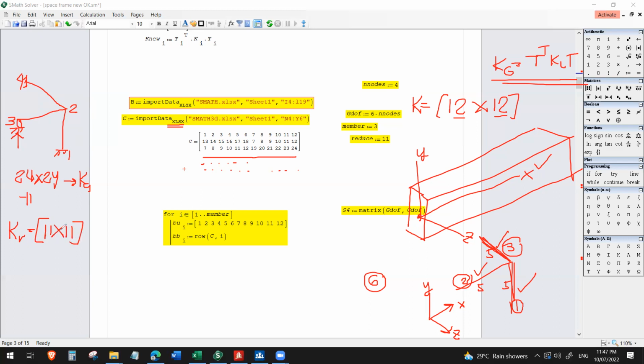So that's the relative stiffness matrix, no? Meaning relative stiffness matrix because we now consider the number of displacements of our structure. No, the absolute stiffness matrix will not consider the supports. Now, since we already consider the supports and the displacements, we have 11 by 11. That's why my code here is 11. Okay, the variable reduced is 11. So meaning the reduced stiffness matrix.